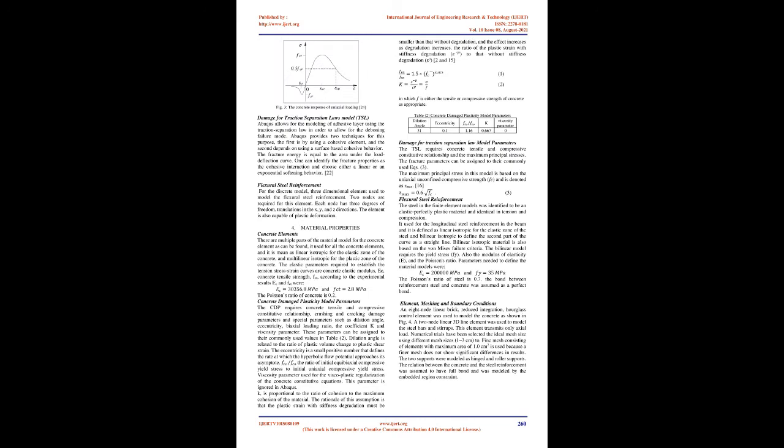Nayak et al. 19 studied the fracture response of notched beams under 3-point bending, simulated using the extended finite element method, XFEM, to determine fracture characteristics. The notched beams of size 330 x 25 x 75 mm were used. Yin 24 used an Abaqus simulation to determine the concrete fracture parameters using 3-point bending beams with specimen dimension and initial crack length 150 x 100 x 750 x 60 mm.